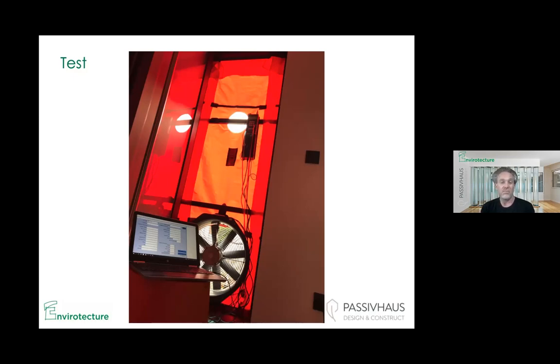The computer works out how much air is flowing through the fan at different pressure levels. It then computes what that translates to as an air change rate for that volume of building at particular pressures, and therefore you end up with a result. They're really quite exciting the first time you get to see it. Once you've seen it once, they're fairly mediocre and a little bit dull.